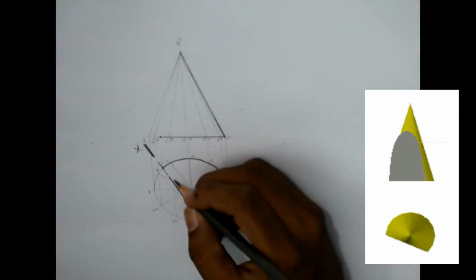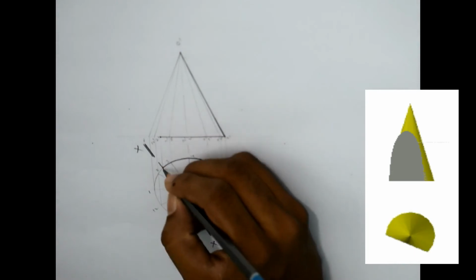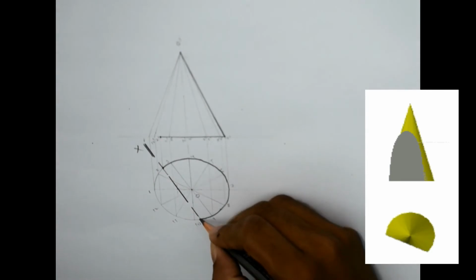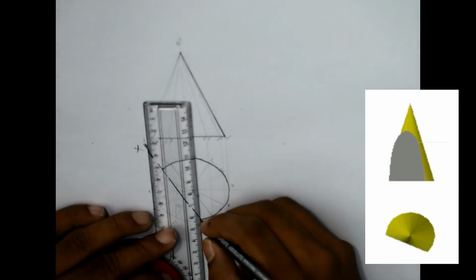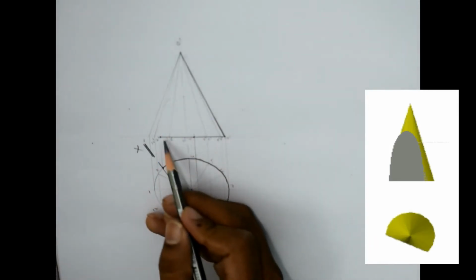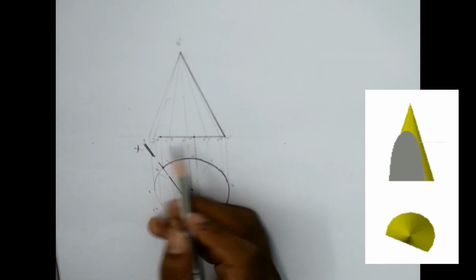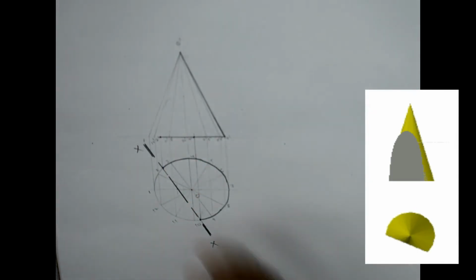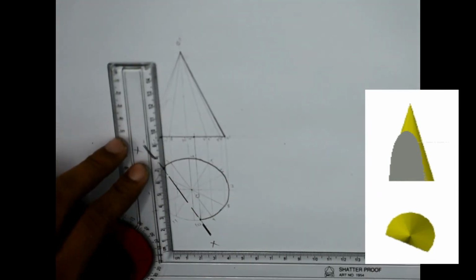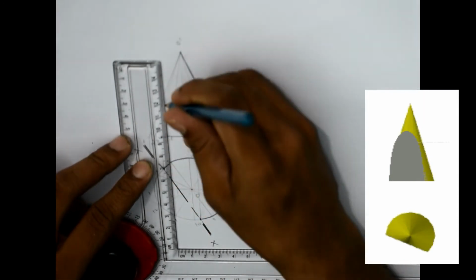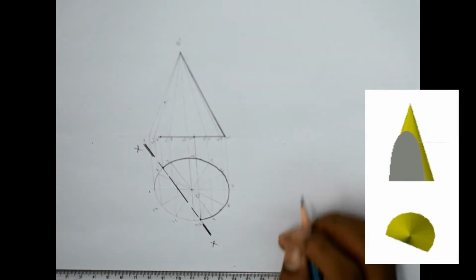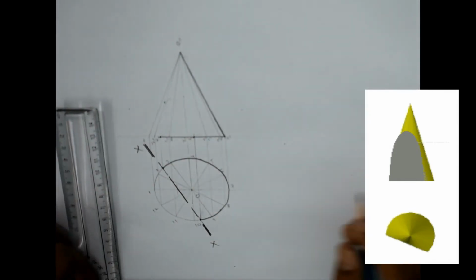So observe that this is the base which is viewed from the top, and this is the base point. So you will get one point here, and the section plane is getting the other point here. So this is the other point. So you know that your parabola or whatever shape will appear, it will appear in this portion only. And also see that this is the second line. So the section plane is cutting the second line here, and the second generator is here. So they will meet here. You have to do this a little bit carefully.